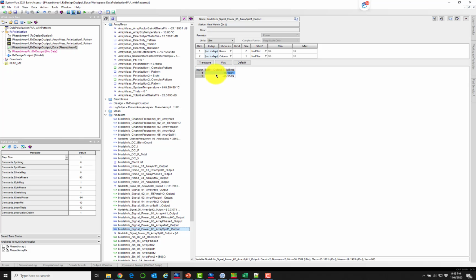As we can see, the E theta antennas together have produced some output, and the E phi antennas produced a very low output. So the question here is that we should not actually ideally see any output from the E phi antennas because the incoming wave has no E phi component, and the E phi antennas ideally should pick up only E phi and not E theta.